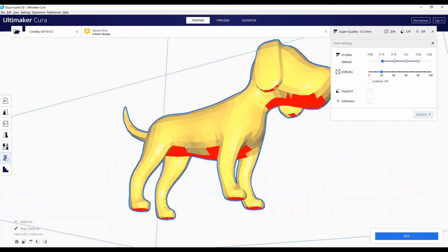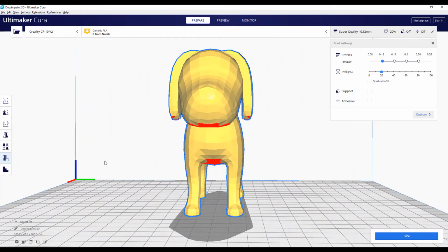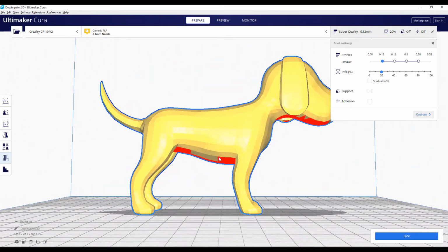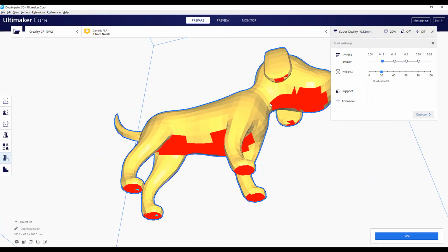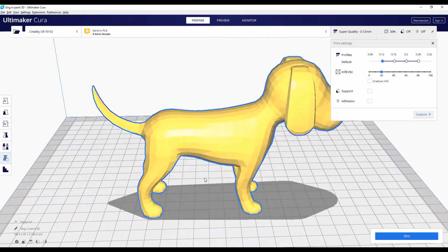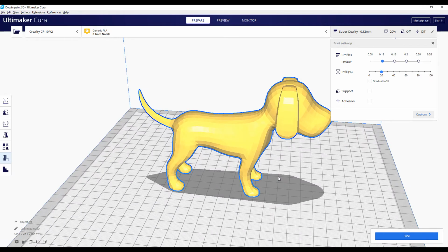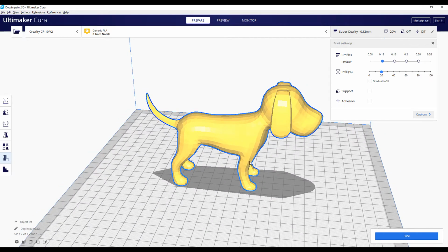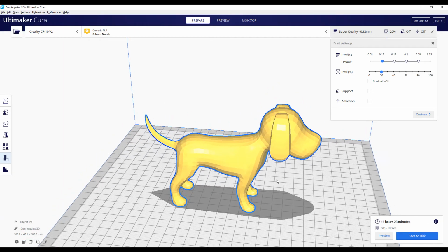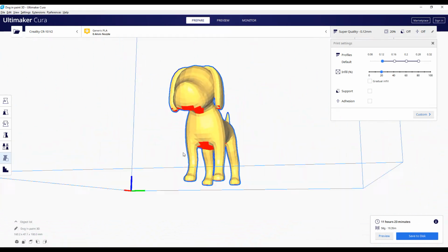It's a way to say it will be strange, and the fact that it's red right here means that the mesh will need some support. We will prepare a preview of what will happen during the printing, and you will understand why the software, Cura, is asking you to create support. So let's click on Slice, and then you will have a simulation of what the printing will be.